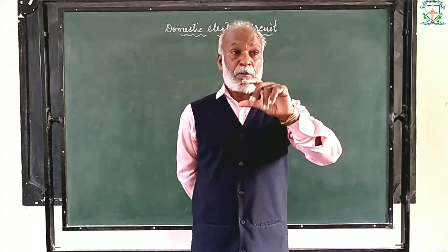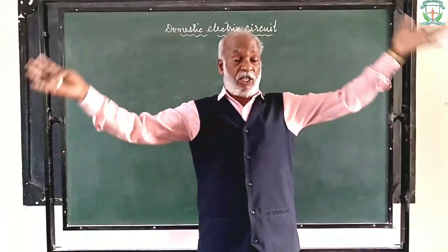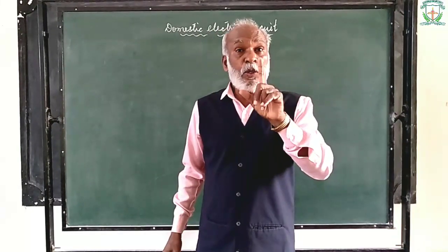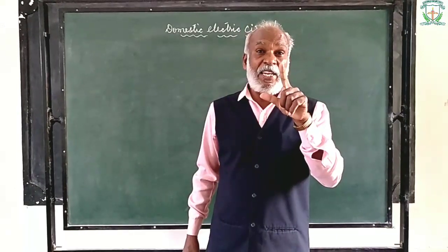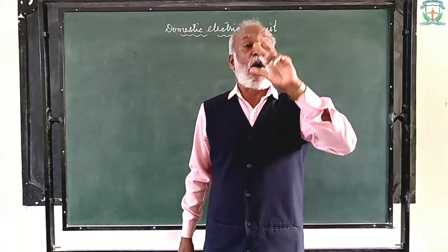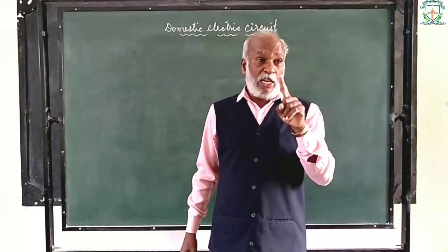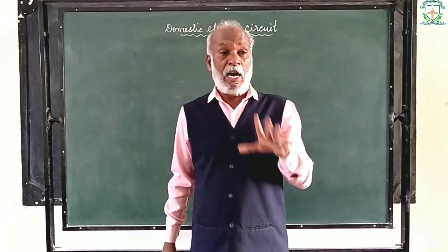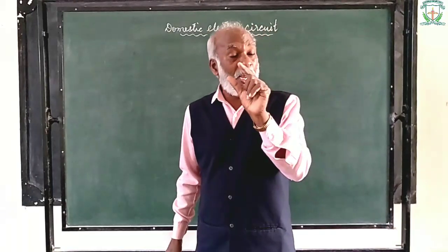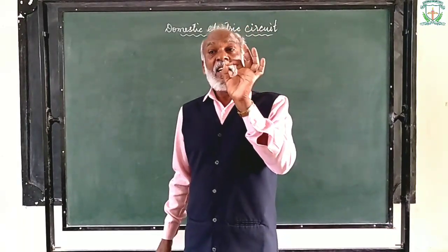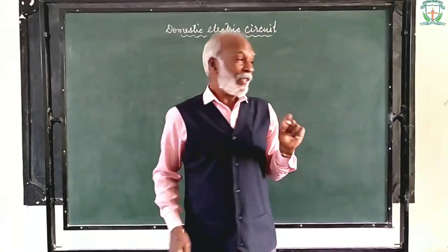So the alternating current generator in the generating station, the large generators, will use 3 coils, not a single coil. 3 coils wound on the same armature, and one end of the 3 coils is connected and it is grounded. So it is like this.